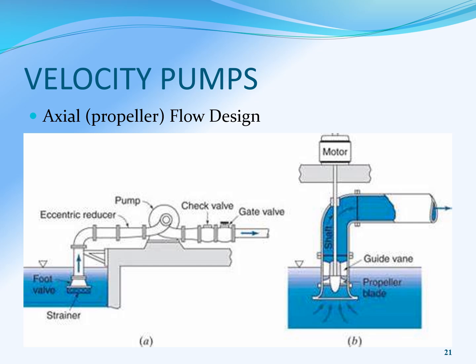The other would be a concentric reducer, which is actually this one right here. It's not labeled, but you can see that it concentrates out into a center point, right? Whereas the eccentric has only one angled side. But anyway, water travels through the pump and then out into your system.